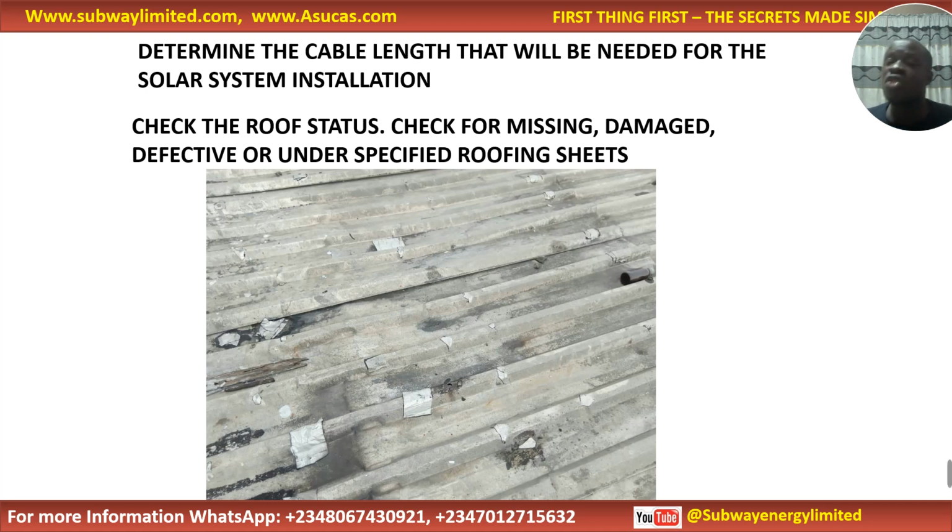You finish installation and the roof is leaking. They will call you. Will you go up there and bring the panels down? The roof man will come and fix the roof. You mount again. When you leave, the roof still leaks because the gauge does not support movement. So please always ensure that you check the roof status. Is it efficient? Is it okay? Is it manageable? Please don't manage. Instead of that, go and look for stanchion, construct and mount the solar panel to protect your image.